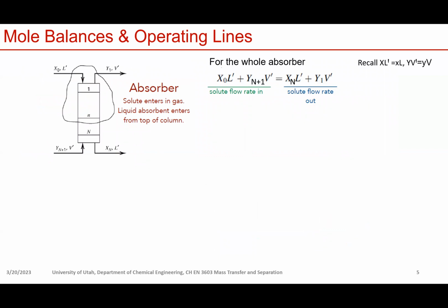Now let's look at the mole balance, right? That's typically how we do things for a separation process. First, let's look at the whole tower as one unit. We look at the mole balance.